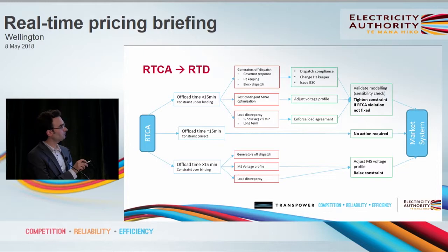The way we model our load is on a DC power flow. So if you apply AC power flow requirements to a DC model, we have estimation factors about how much reactive power is required, and that can have an impact on branch flows. So reactive power results in more current flowing across a branch, which affects offload times.